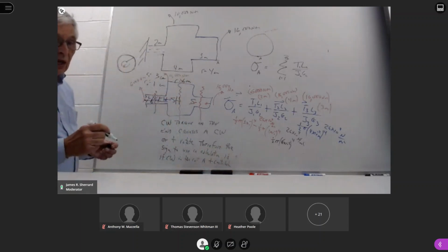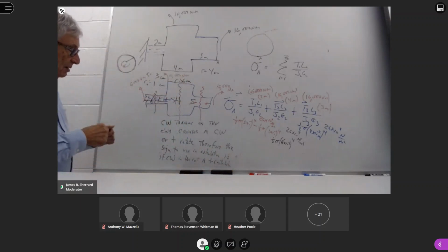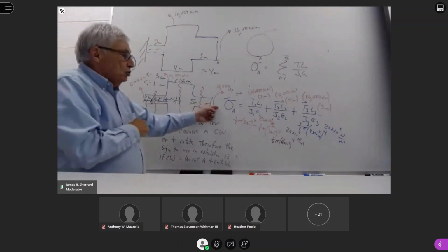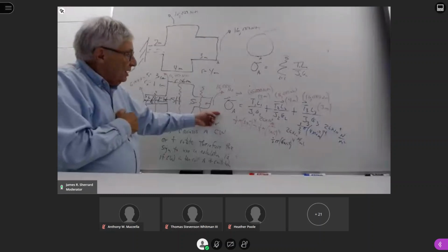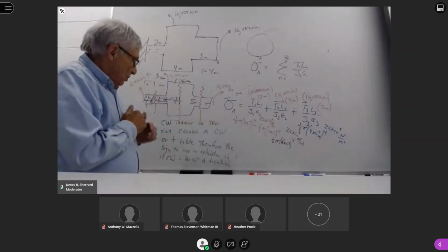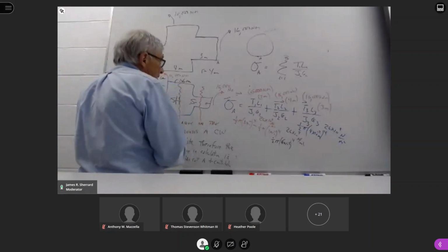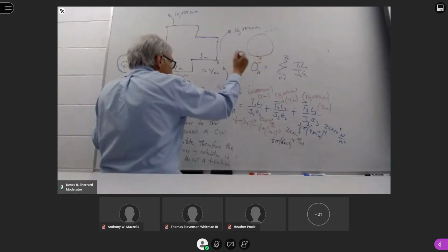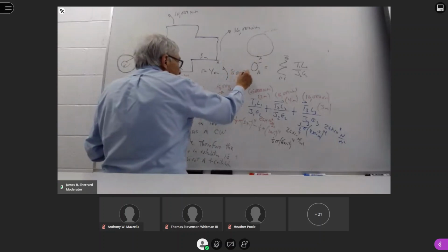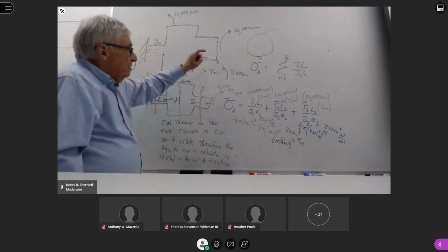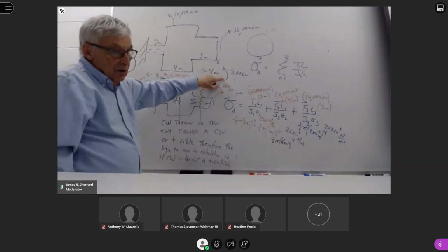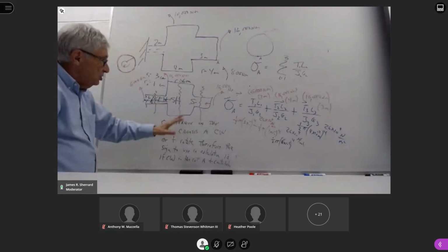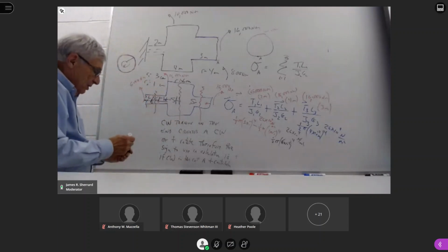Again, you could set this up any way that you want to. This is the one that I typically like to do. In other words, I always use the torque that's on the end. I look to see which direction it was going. For example, if this was going the other way for some amount, I would say counterclockwise at the end will result in a negative rotation. And then I would use that same analogy going back through each section.